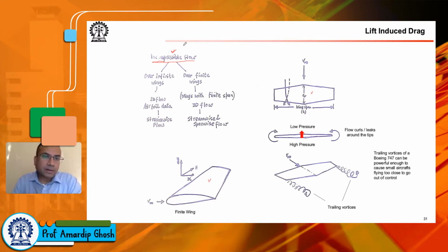However, if your vehicle is flying at a decent Mach number, which you suspect could be in the neighborhood of the critical Mach number, then you have to take care of aspects such as the presence of wave drag. And if your vehicle is flying at velocities or Mach numbers above 0.3, remember that is the compressibility range. Above Mach 0.3, compressibility comes in. You might do a better job if you do the Cp corrections. So instead of using Cp, it might be better to use Cp equals Cp naught divided by the square root of 1 minus M infinity squared, that is, the Prandtl-Glauert correction for compressibility. You have to keep these aspects in mind when you are given a problem, or when you face a problem.